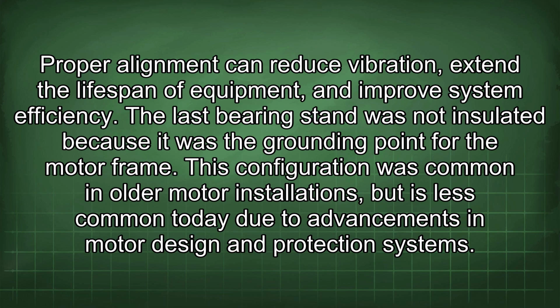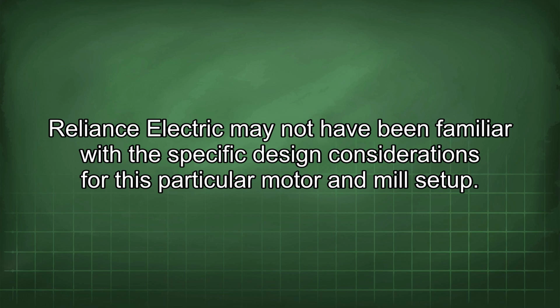The last bearing stand was not insulated because it was the grounding point for the motor frame. This configuration was common in older motor installations but is less common today due to advancements in motor design and protection systems. Reliance Electric may not have been familiar with the specific design considerations for this particular motor and mill setup.